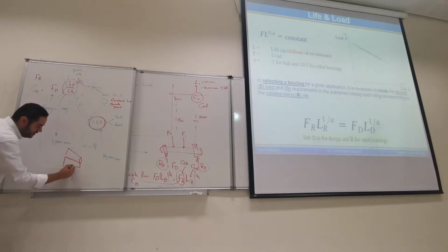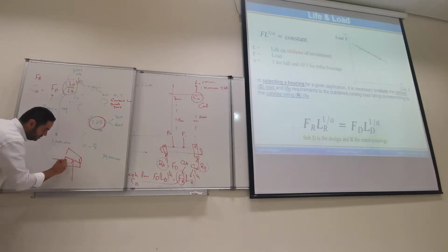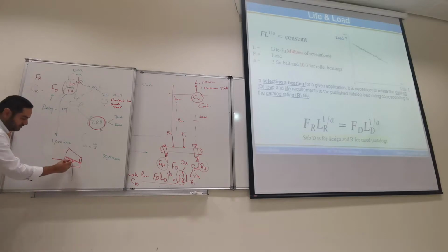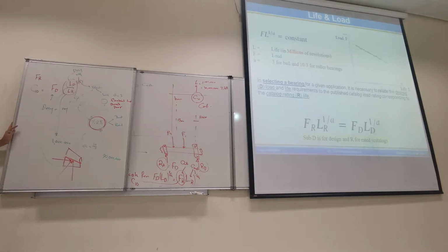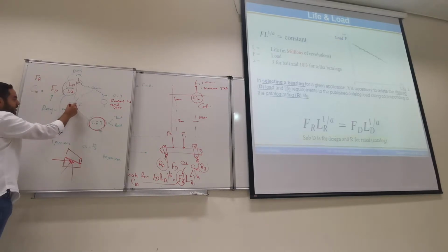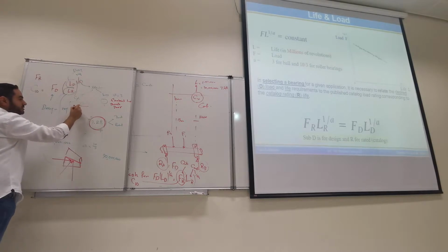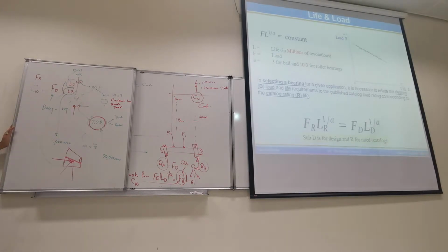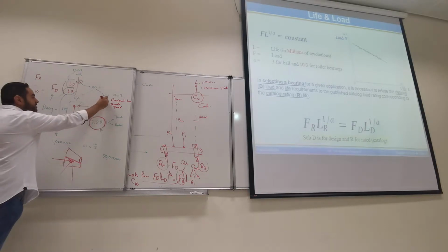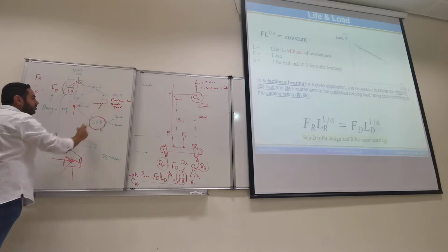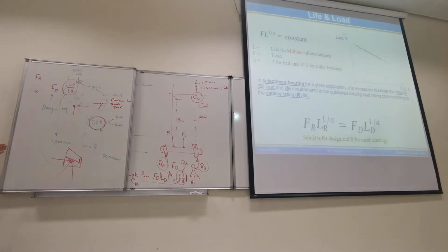So when you have the radial load and thrust load, their resultant can still form a perpendicular to the surface of contact. But for the cylindrical, the radial load is perpendicular while the thrust load is parallel, horizontal, so the roller will slide or slip. For the ball, it can, because the contact is a point, so I can carry both, but there is still a limitation on the thrust load.